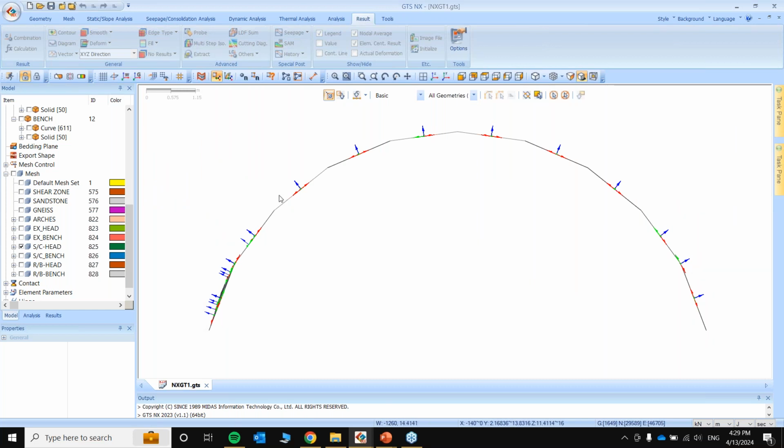So here the Z is out of plane. That is what we wanted out of here, because it's a 2D element, the plate element. So you can see it is completely aligned. If you have triangular elements, then the alignment becomes very, very tough. That is why in these cases, we always recommend, if you want to check for hoop stresses, directly go for hybrid meshes. This is where you will save a lot of time. Again, calculation time can become less. That is also true. But the primary goal is getting the alignment correctly.